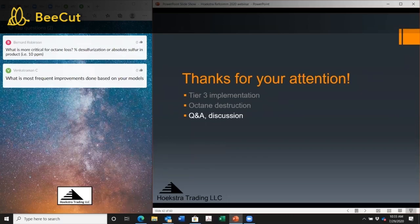Okay. It says to prevent gasoline octane destruction, one option is to pre-treat the cat feed, but that may be very expensive. Right. Another option is to blend it with a reformate to boost the octane. Yes, that is something that refiners are doing, but it costs money to replace the octane that you destroyed in the gasoline desulfurizer. So it comes at a cost. I think that may be the point I missed. Go ahead and read the rest of it, Becky, please.